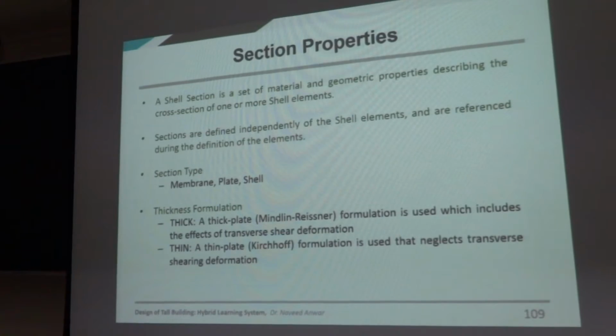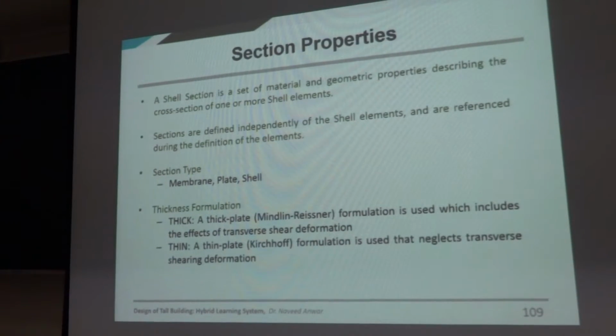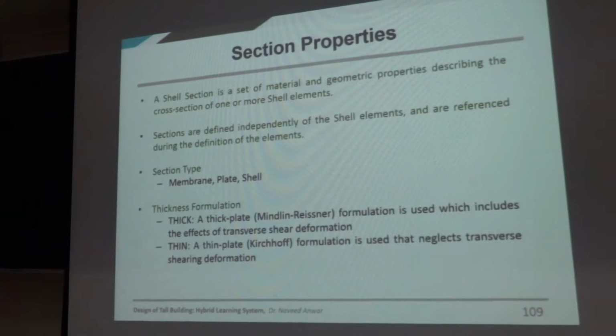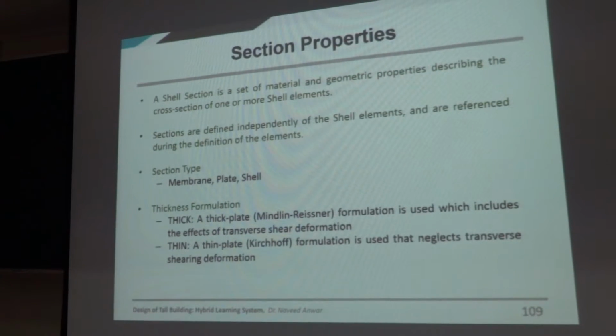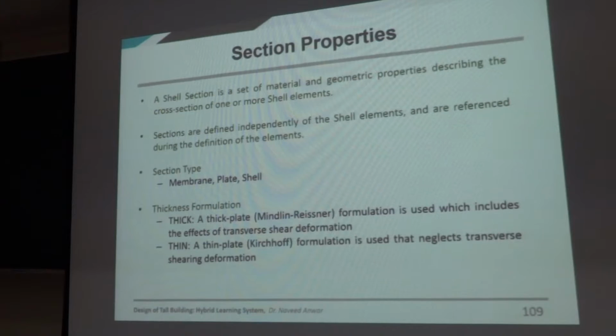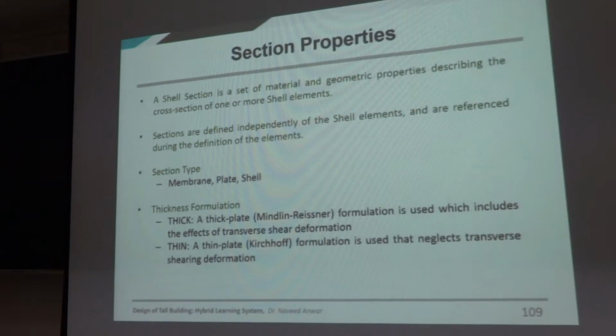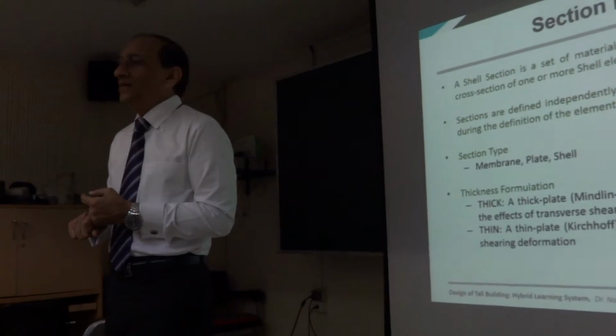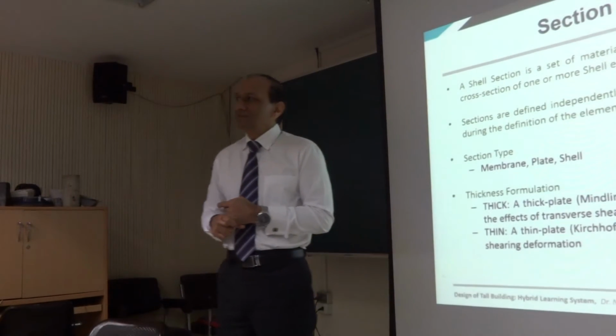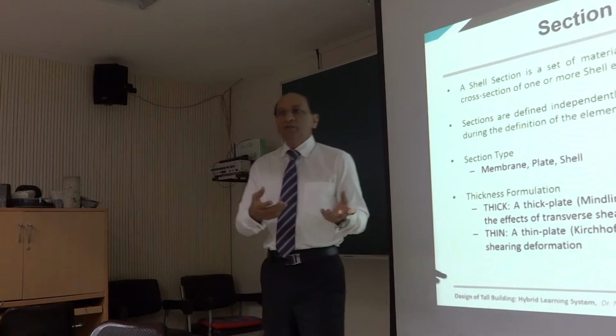modeling of the plates. How many properties do you need? Two-dimensional elements, how many properties do you need? Just thickness plus E and G and maybe mu, so maybe 3 or 4, right? Because G can be calculated from E. So mu. So basically thickness, E and mu. These, what is mu? Correct. So you need those, and then you define this one.